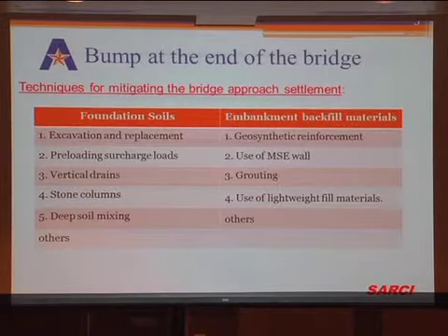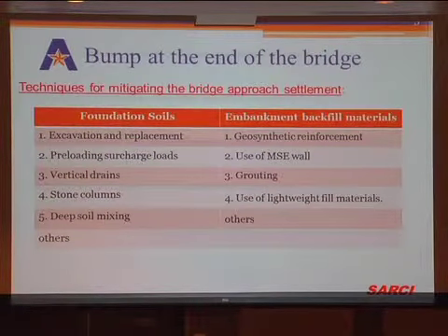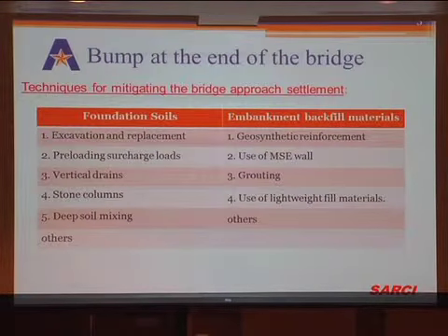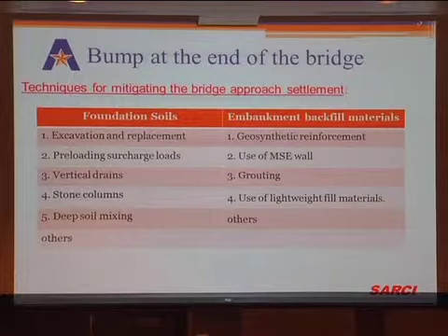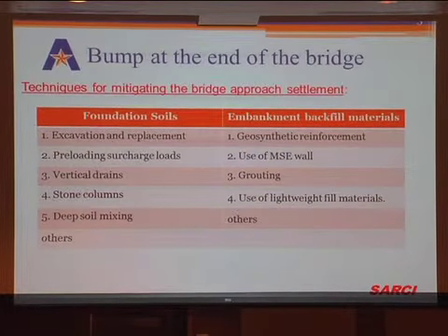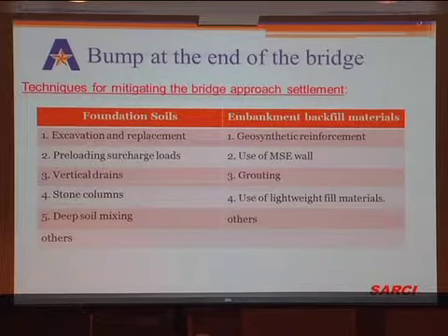What are the different ways you can repair them? Here I put only a couple of them. There are other ways you can repair them. You can work on the foundation soils. The one I listed here is excavation and replacement. Remove all the foundation that is bad, nasty clay, which consolidates a lot. So remove that and put in a good quality fill. And again, that can be expensive, but that has been tried.